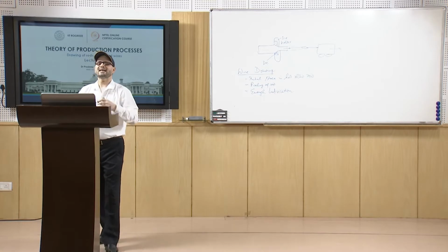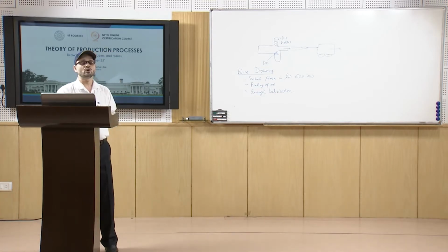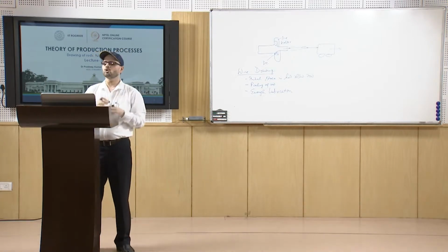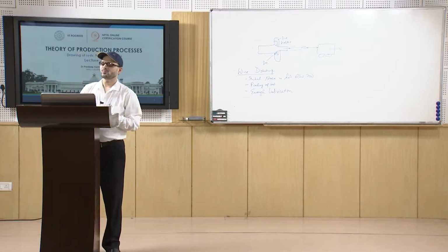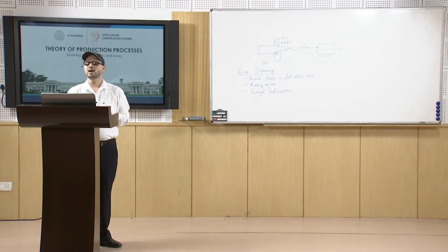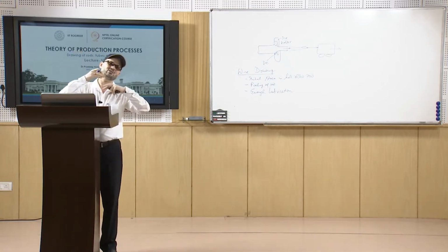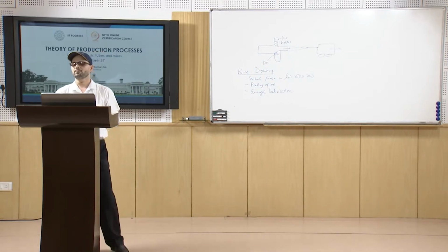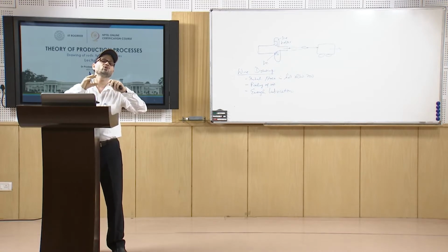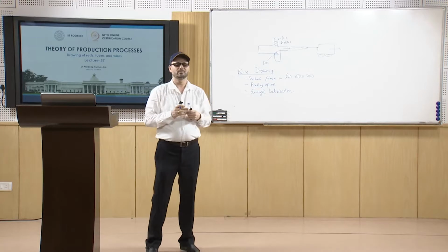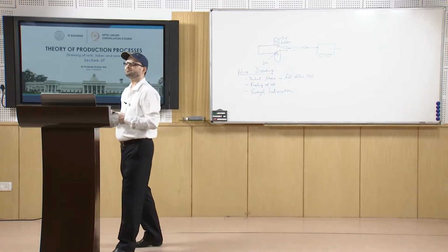You also use certain conversion coatings, like sulfides, sulfates or oxalates, applied on the rod. They are used in conjunction with the lubricant, like soap in the drawing operation.